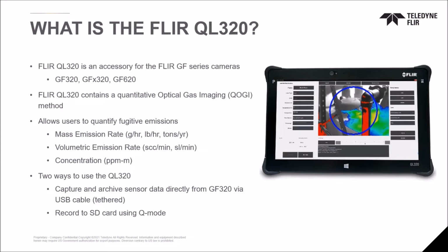That just simply tells you a concentration in that area. And we can actually measure a concentration over a 1 meter distance. And it's an average of the intensity of that pixel over that 1 meter distance. And a parts per million meter in other technologies is becoming more and more accepted within the various industries that we operate in and the various entities that are utilizing a quantification solution.